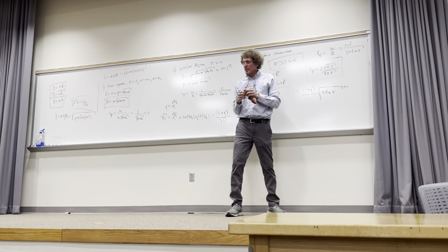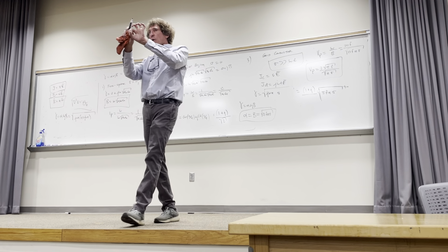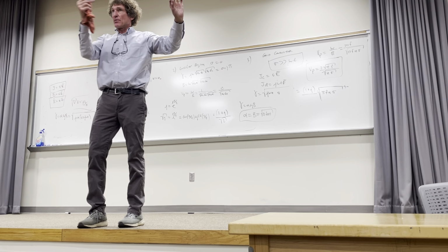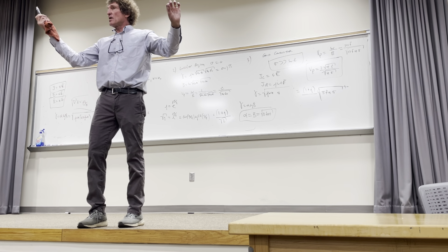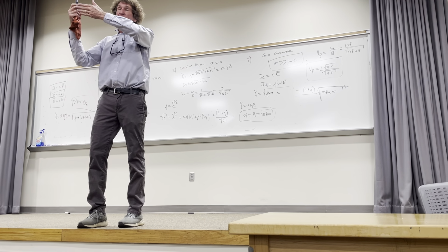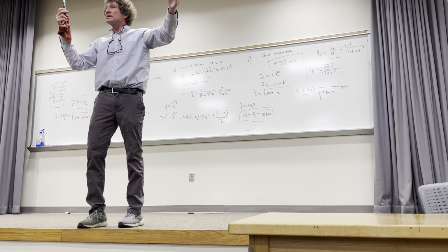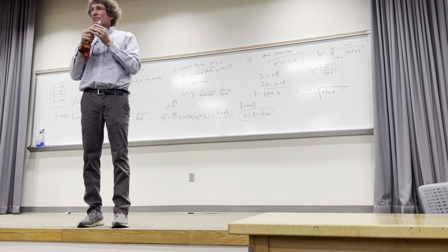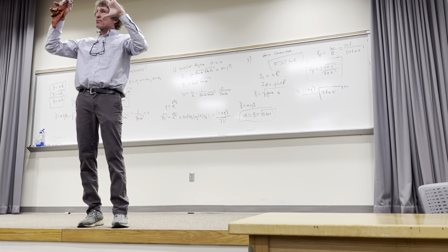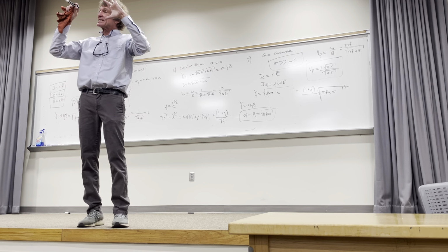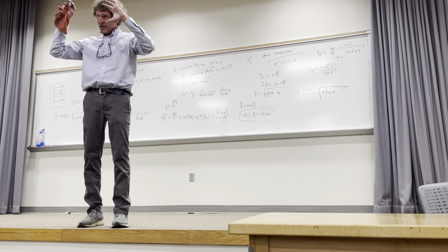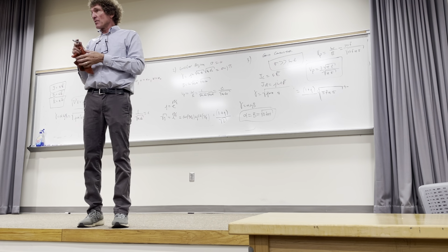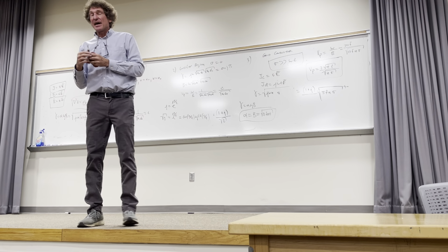Here's the thing about that, and that people get messed up on. If you have a conducting wire, and you drive a differential input, you get current flow, right? The actual velocity of the wave, if it's a propagating wave, on that wire is going to be about the speed of light. It's really due to the dielectric between the insulating wires. However, if you had a big fat wire, the rate that the actual electric field propagated towards the center of the wire would get slower and slower and slower and approach zero. And this is one of those weird things.